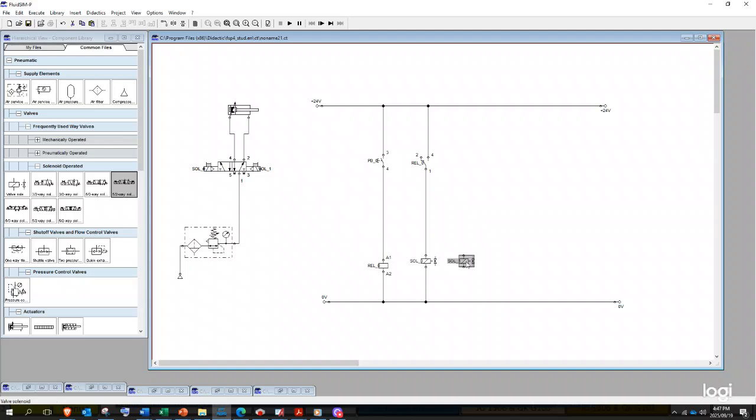Well, it doesn't matter whether I start with my valve solenoid and my changeover switch or my relay. The structure doesn't matter, as long as it's properly connected using the principles of FluidSIM. If it's indirect actuation, your relay connects with your inputs, which are your sensor and your push buttons.